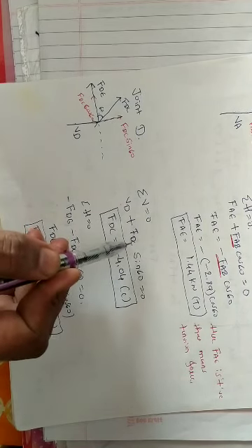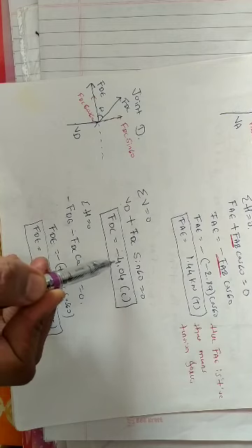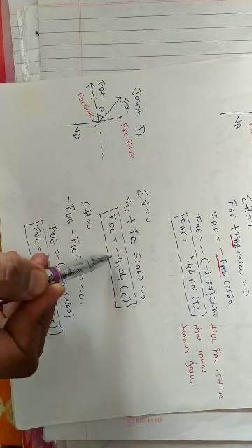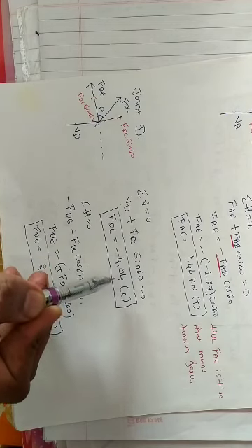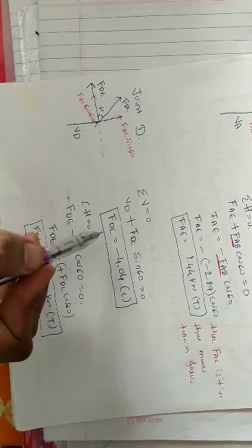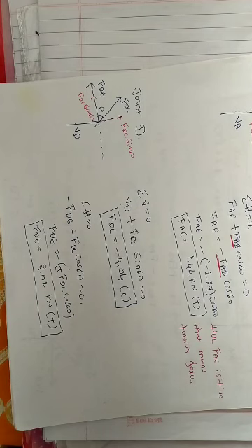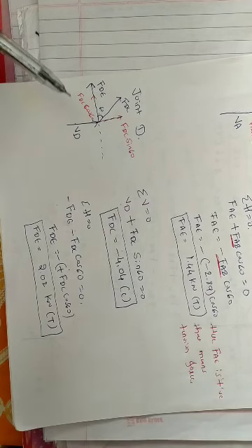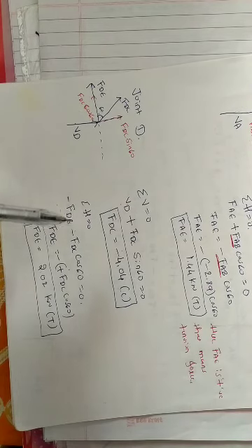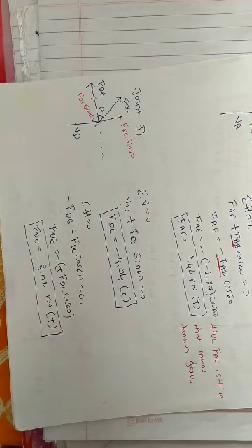That implies FDC is equal to minus VD divided by sin 60. The answer we got is negative, that is minus 4.04. That implies the force is compression. So we'll write FDC is equal to minus 4.04 compression. Next condition, summation of horizontal forces is equal to 0. So for the horizontal forces, FDE is acting along the negative x-axis, so minus FDE, and FDC cos 60 is acting along the negative x-axis, so again we'll write minus FDC cos 60 is equal to 0.